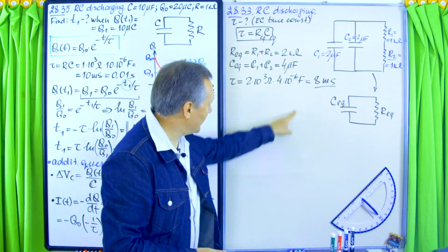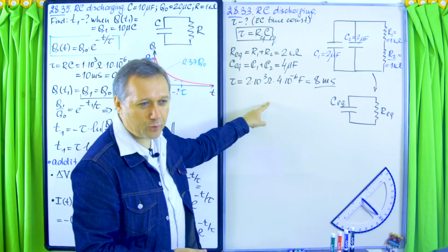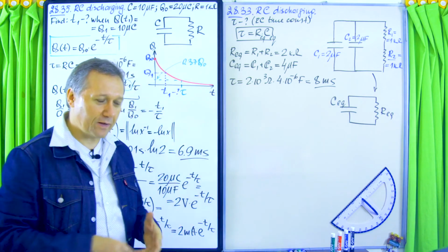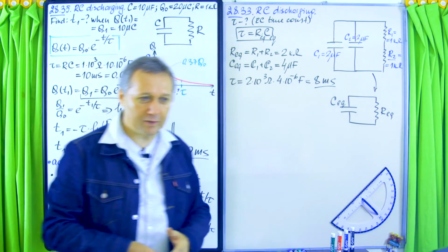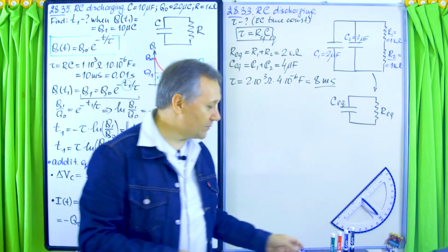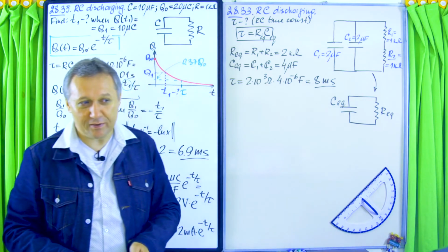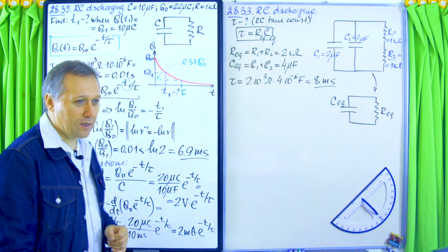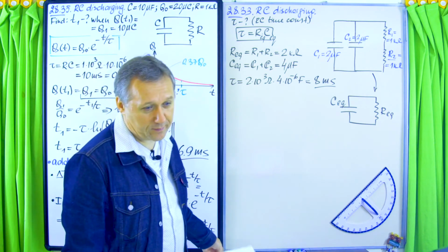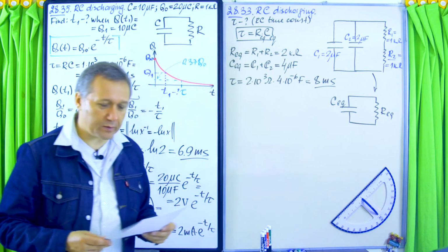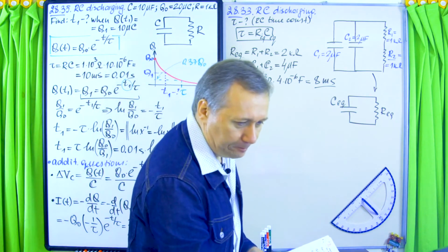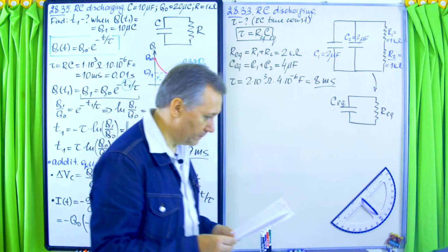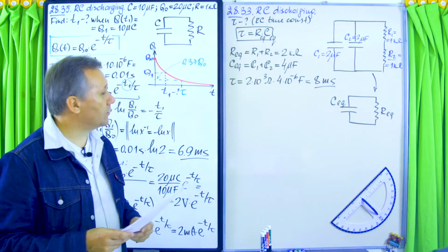So instead of square pulses, we had a short pulse where the voltage was increasing for some finite period of time, and then it decayed over a finite period of time, and it helped: the bistability disappeared. Then we wrote a few papers and we used those pulses to drive our lasers. So it's quite a common situation where RC circuits are used, as I said, for filtering noise. Okay, and so you see it's not complicated.